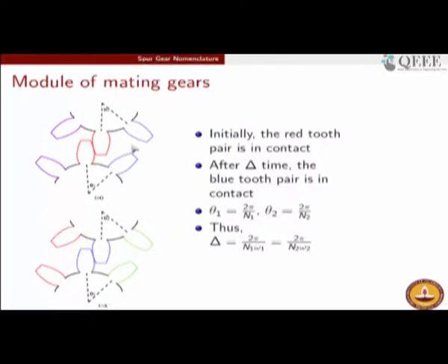But as we have argued, the time taken for each of these teeth sitting on two different gears must be exactly the same, only then will the picture completely repeat after every engagement. So, we must have these two quantities exactly the same, and this essentially means that the number of teeth is inversely proportional to the rotating speed.